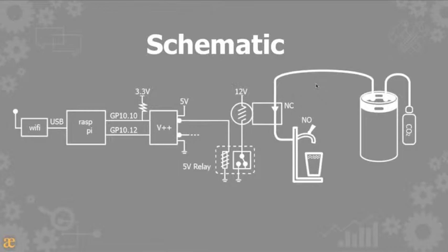And that was an NPN transistor, so it actually inverted our logic. So really what we would do is drive a pin high to turn the solenoid off and drive a pin low to turn it on. I think that was how it worked anyway. There are so many different places that you can invert the logic that we just set some values, and if it didn't do the right thing, we flipped it around.